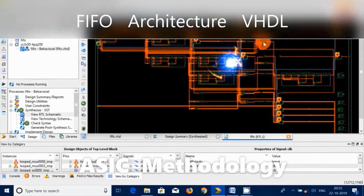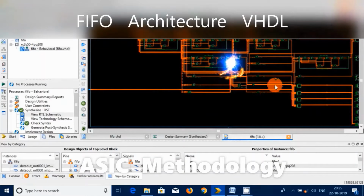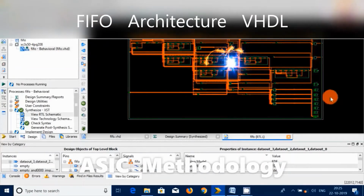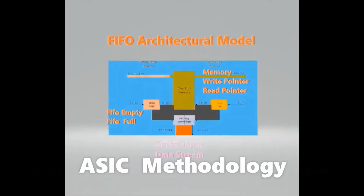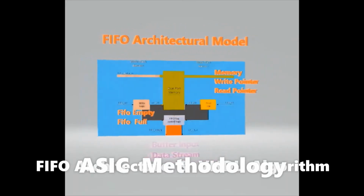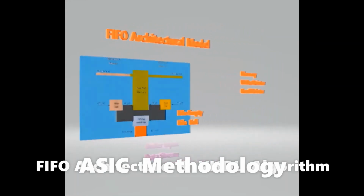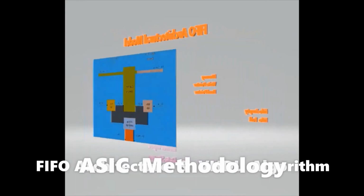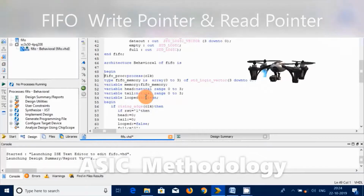The FIFO is used to buffer the minimum number of burst data in order to guarantee continuous reading from the FIFO without interruption. In this case, the FIFO read control logic block checks for the almost empty flag going high and sets the FIFO read control signals to read continuously from the FIFO.